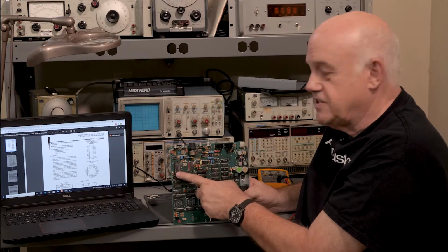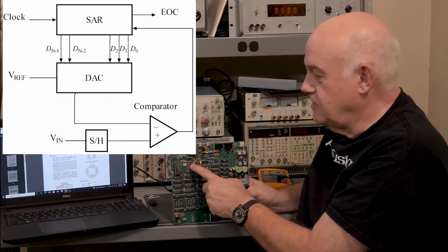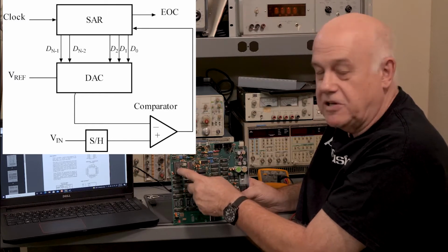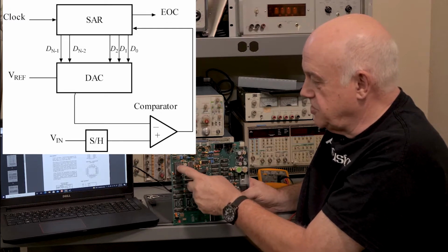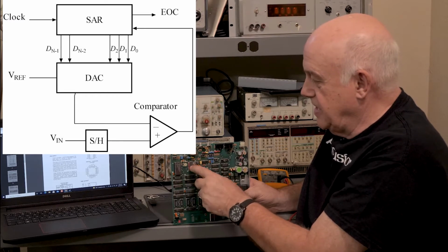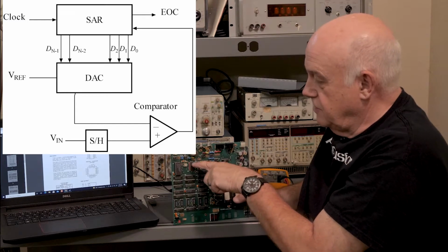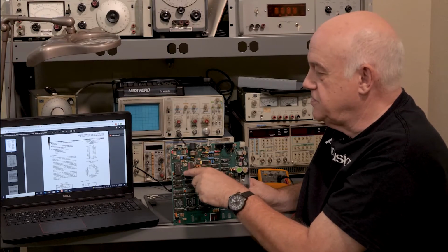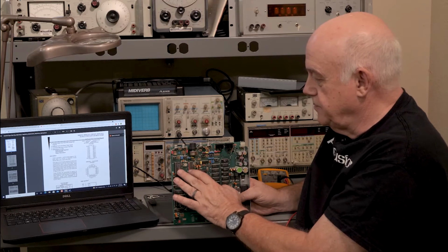Well, it turns out what this chip does is it turns a D to A into an A to D by running its little, there's actually a little, what we call a state machine in here, that runs a little series of instructions very fast, and the DAC and this comparator right here form an A to D converter. And so as long as it runs fast enough between our sample period, it'll convert.